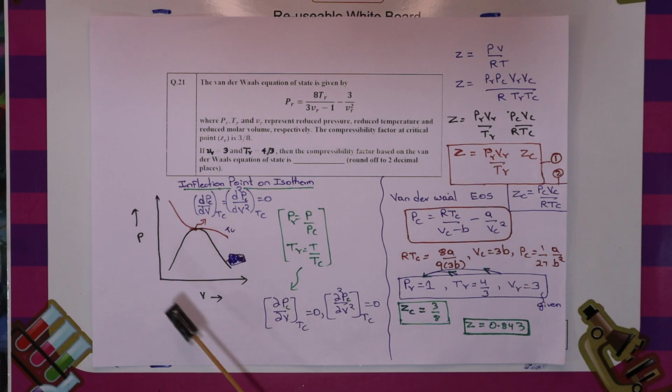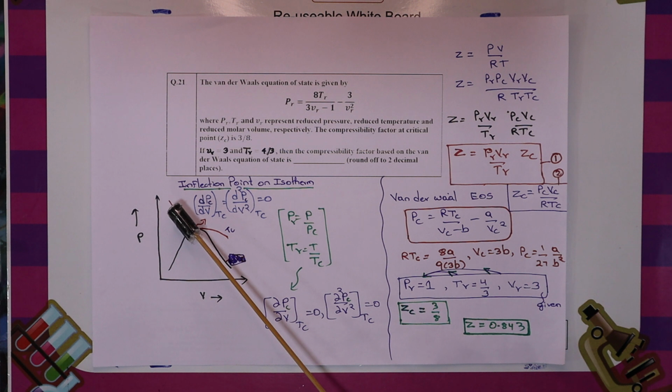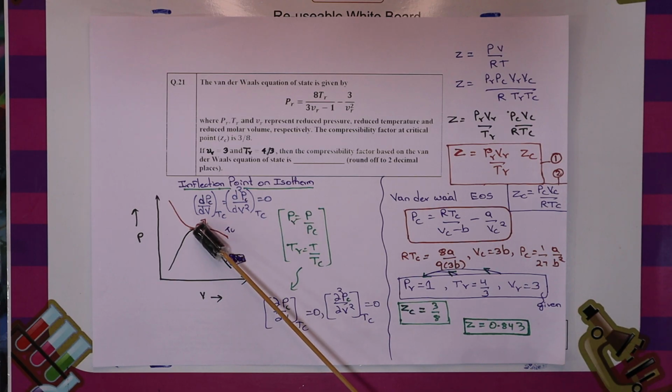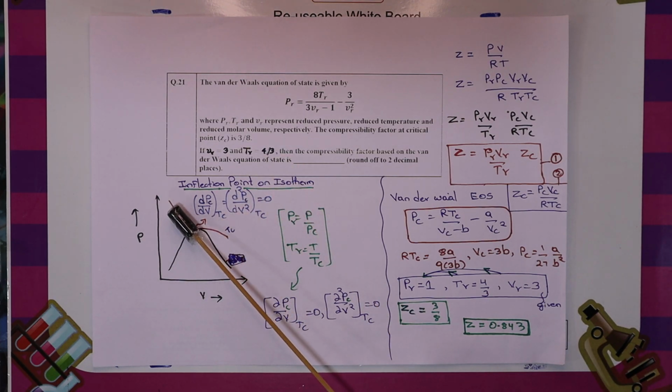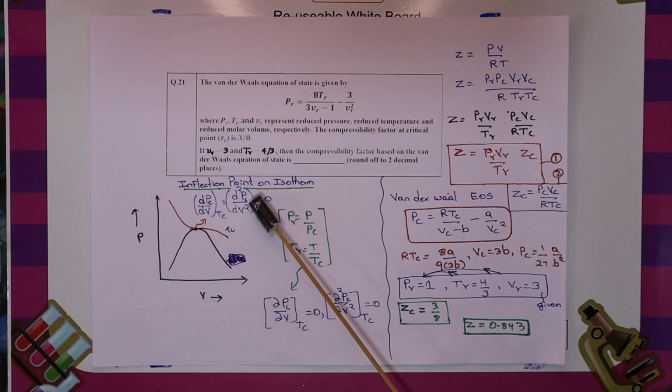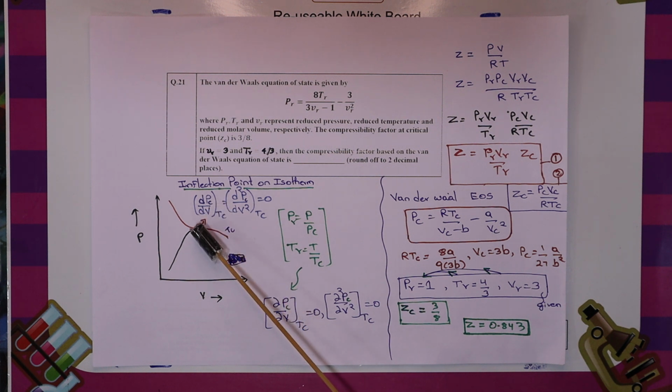If you look at the PV diagram, at the topmost peak the isotherm goes this way. At this particular point, where the graph is between pressure and volume, the curve takes a turn and becomes flat, at the critical state, at critical temperature. The curve goes through a flat region. Here the slope of this line is 0, it is flat, and the second derivative of this line is also 0.